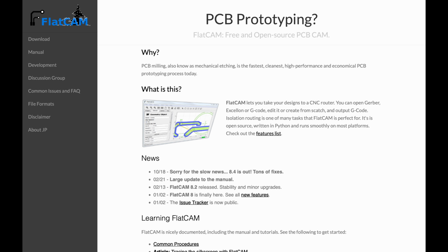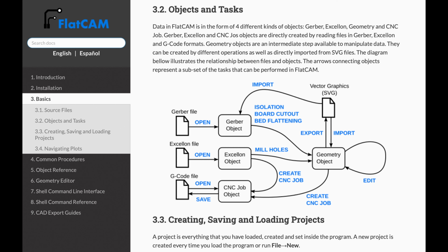FlatCAM is an open-source PCB computer-aided manufacturing software. It takes as input Gerber and Excellon files, which can be generated by PCB design software, and outputs G-code, which can be used on a CNC mill to create prototype, single-sided or double-sided PCBs.